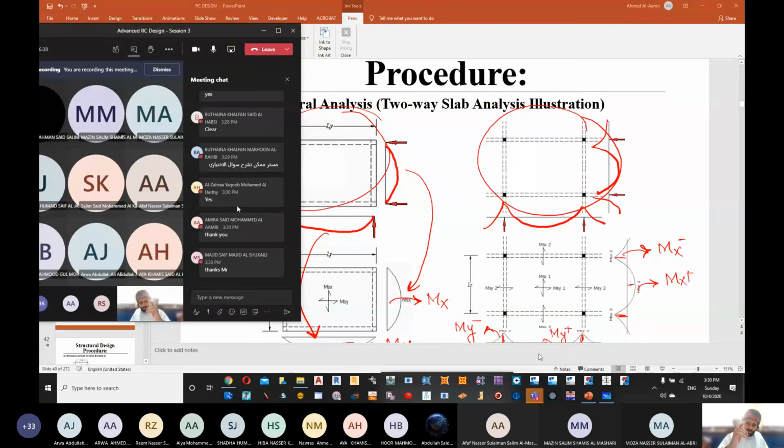Those who are having a class can use it. Those who are not having a class and want to listen to this particular question can sit. Now, when we talk about one-way slab and two-way slab, the main difference between them is how many major moments there are. When we talk about one-way slab, it means that this slab bends in one direction, with a major bending moment in one direction and the other side very minimal, while in two-way it goes in both directions. I'll try to illustrate it for you